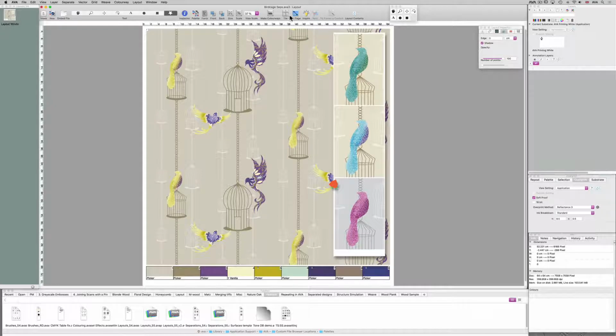So I'm going to use the tile function, and I'm going to select one across, and I want a total of 9 objects. So because I've put one across, it will tile them down the way, and I want a spacing of 0.1. Click OK, and that will tile them down like so.